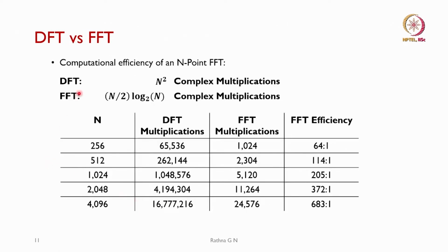So, now we have compared when we discussed DFT versus FFT. Now, after doing the FFT splitting, we will be seeing how we have reduced it. So, we know that we need N squared complex multiplications in DFT, whereas in FFT, with the shifting of our twiddle factor to the input stage, we have achieved N/2 log2 N complex multiplications.